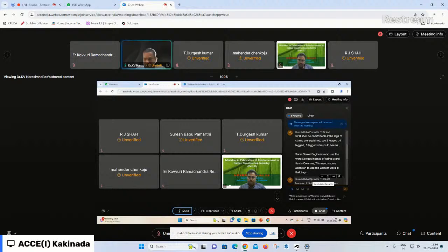That is meeting the development requirements, not only the tension steel requirements of the cantilever, the portico, or we can say the cantilever sunshade. In addition to that, the development length can be met in the form of a stirrup enclosement that meets the development requirement and also the stirrup requirement of your lintel beam.